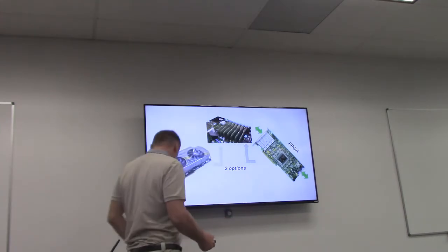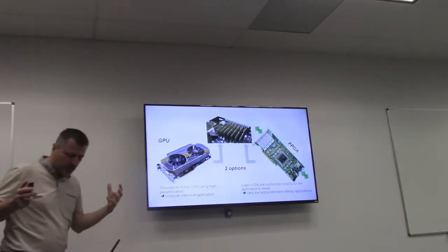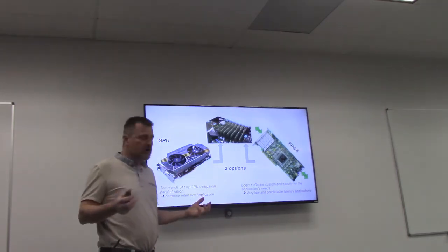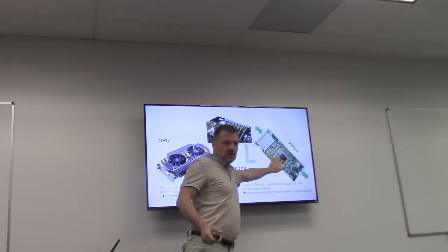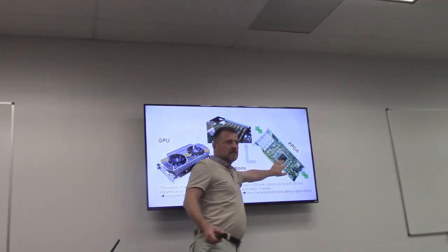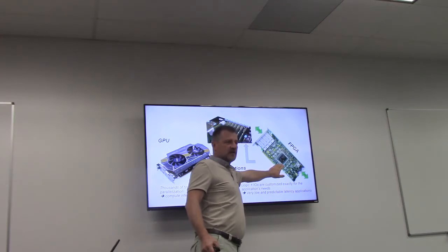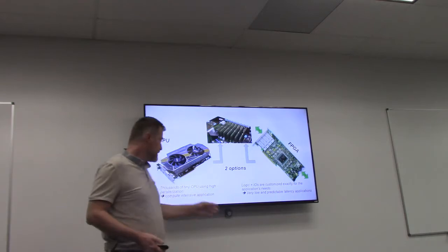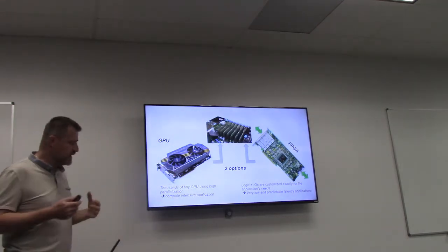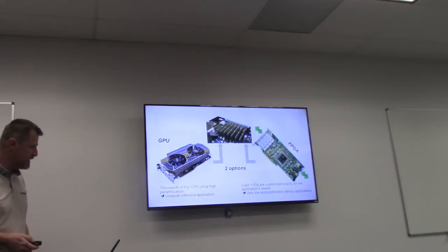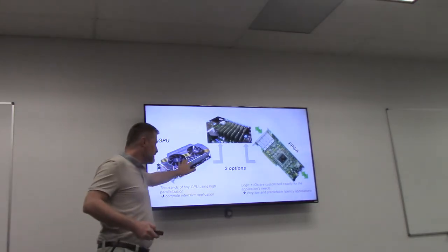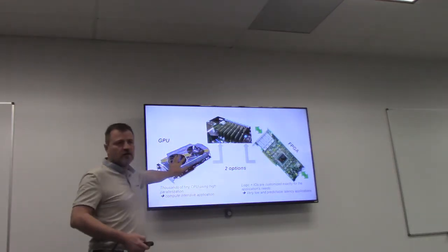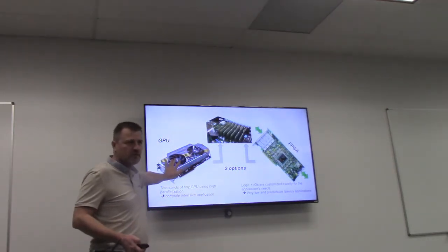And for sure, the second option is to have a GPU. It's not a comparison saying one is better than the other, but there are different things that we can do. For example, in terms of power consumption, because the FPGA is making dedicated calculations that you have decided to build inside it, it generally consumes much less than an equivalent function that will be run in a GPU. For sure, GPUs have advantages and FPGAs have advantages, and these are well known because they have been programmed for years now, so it's very well-known technology.